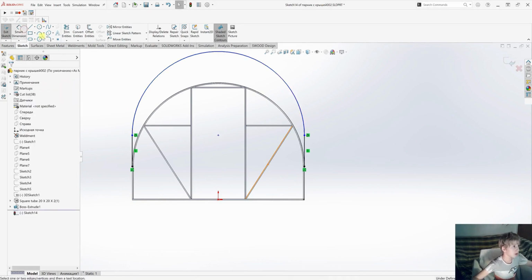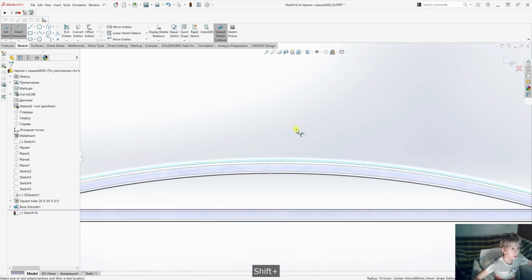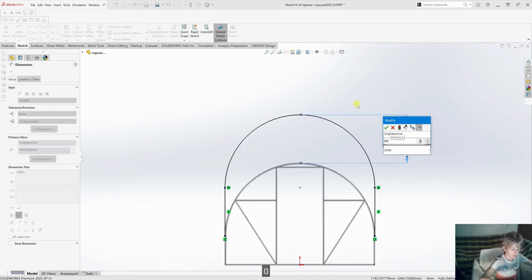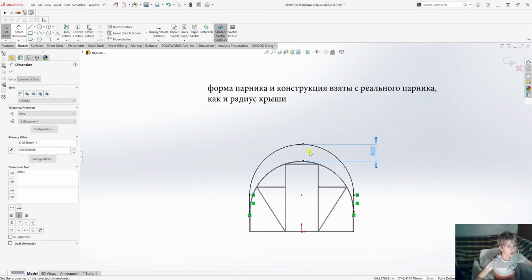And set the thickness to 1/2 meter. I chose 1/2 meter based on my own observations, since that's about how much snow usually piles up if you don't clear it. If you have a different experience, calculate it yourself for your own thickness, 500 millimeters. I made the snow this shape because it slides down the sides, so it ends up looking like this.